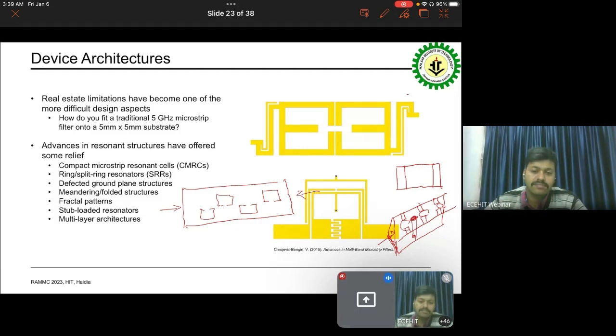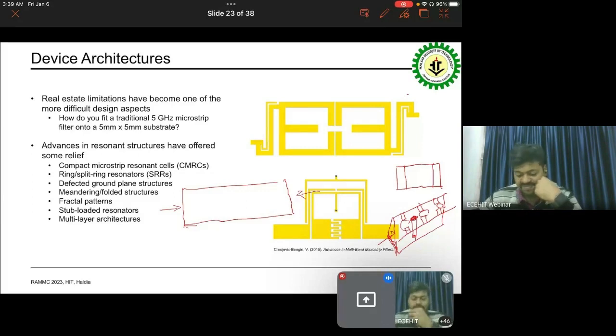But everything that we've applied here is also applicable to the substrate integrated waveguide, so a lot of the mechanisms are almost identical. For the SIW, as opposed to those rectangular iris-based windows, we'll usually use a set of discrete vias. Of course, this will be symmetrical, so it'll look something like this. You'll notice this is very common in a lot of the papers for SIW, and this will stretch over to this side, so it's symmetric.